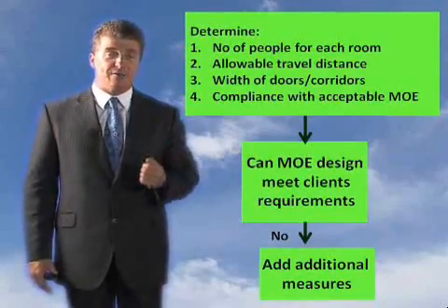So now you're asking for flexibility. Now this code is allowed to be flexible, and what it says is you can vary it in 3 ways. First of all, you can put sprinklers in. Now, if you put sprinklers in, it reduces the risk profile by a factor of 1. An A3 becomes an A2. An A2 becomes an A1. A B3 becomes a B2. That's the first thing you can do.